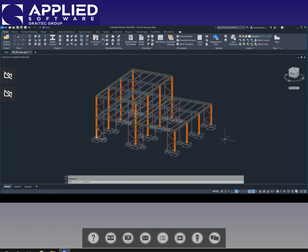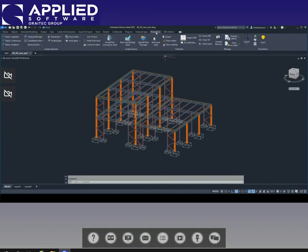So the workflow that I would like to use here to send my steel structure to Advanced Design is going to be through our Power Pack. So I will click here. And in Power Pack, we have an export, import, or synchronization option. In this case, I want to export my model. So I will click on export.